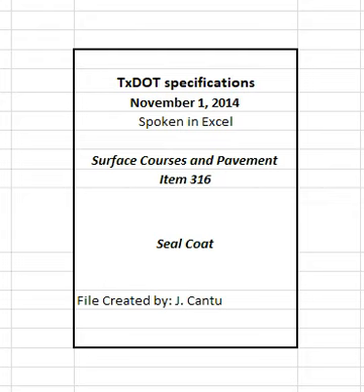5.1.1 Volume. Asphalt material, including all components, will be measured at the applied temperature by strapping the tank before and after road application. The distributor calibrated strap stick will be used for measuring the asphalt level in the distributor asphalt tank. The certified tank chart will be used to determine the beginning gallons and the final gallons in the distributor tank. The quantity to be measured for payment will be the difference between the beginning gallons and the final gallons.